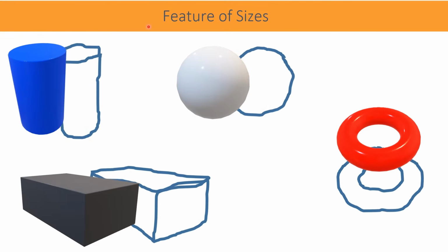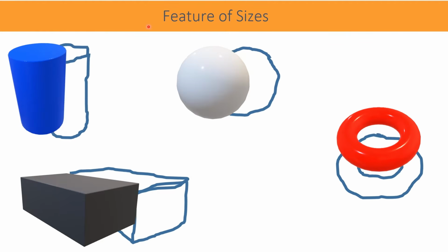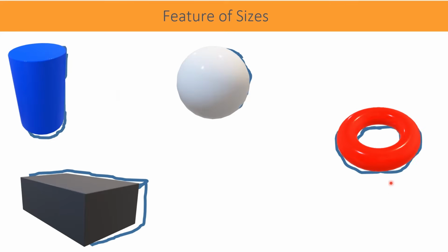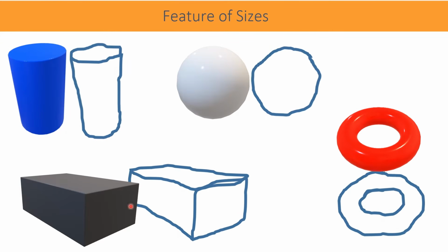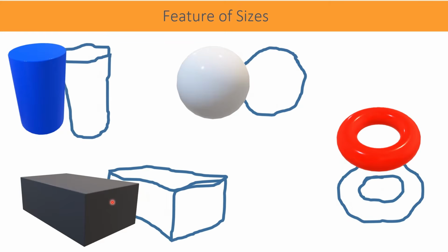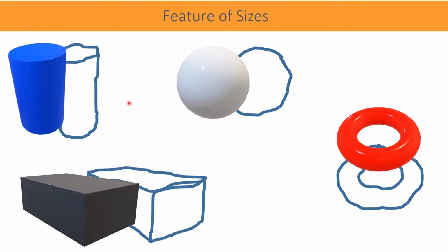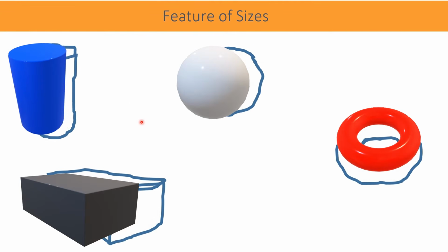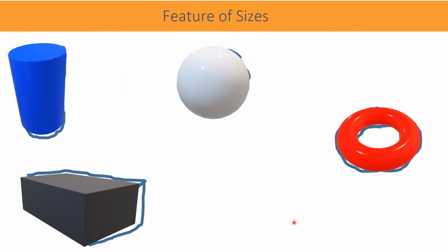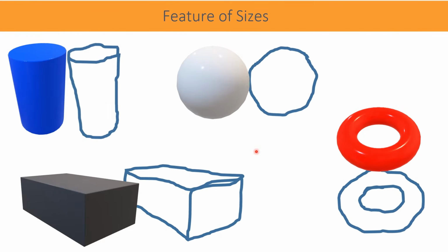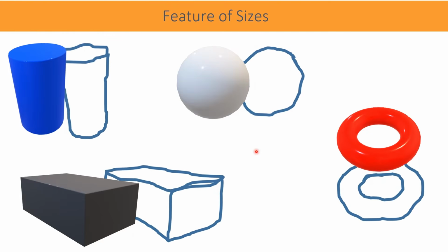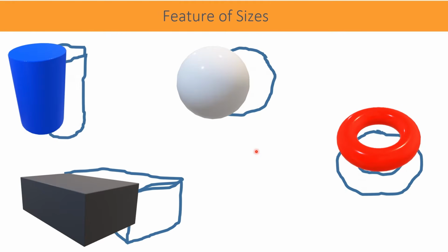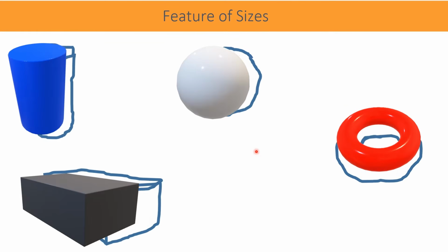For the designers designing the product or the part with their shapes and sizes, and after that producing it on a mechanical engineering drawing, the shapes they draw are without any deviation for the size and the forms. It means all the features they produced on the drawing are nominal. But in the real world it is impossible because of economic and some other reasons. Therefore, a certain amount of deviation is already allowed by the designers.